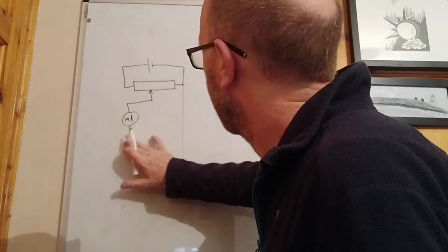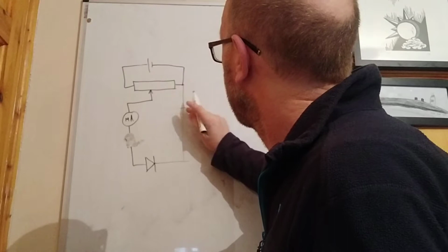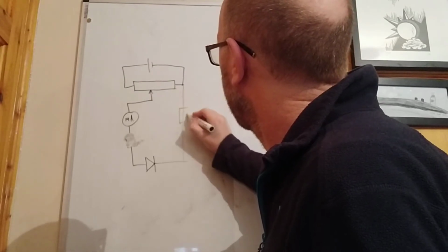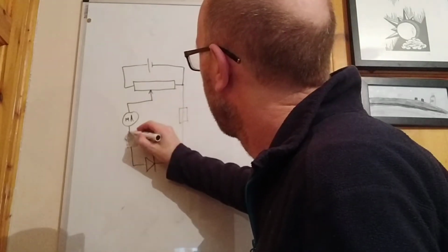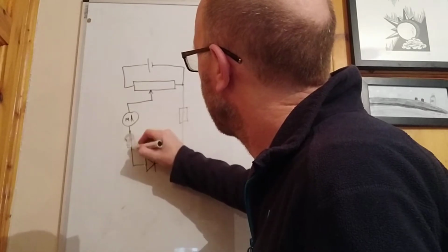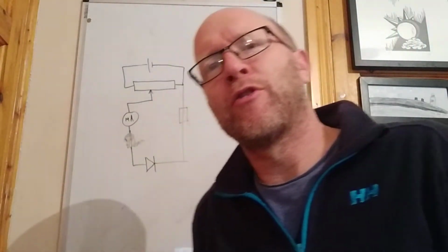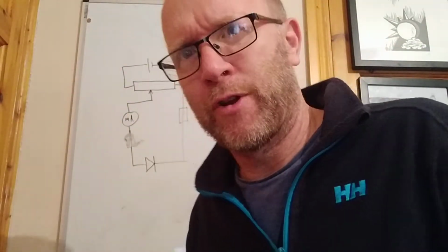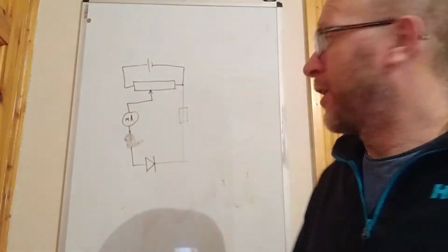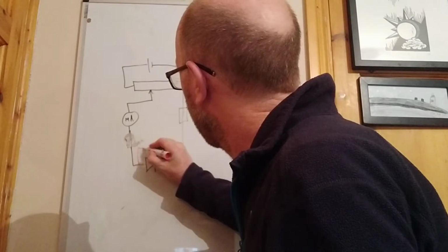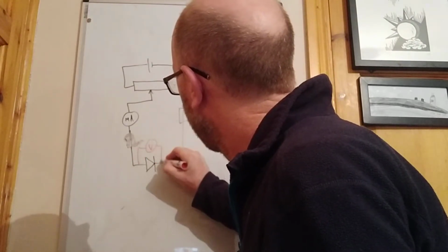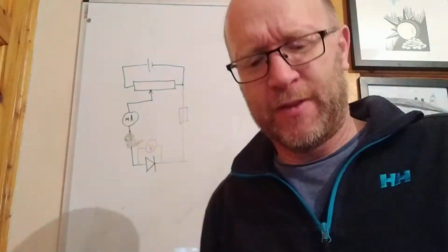Sorry, I'm going to put this resistor over here. We're just putting that in for the crack, really. And remember, at all times, to get the voltage, you apply the voltmeter across what you're interested in. So I'll use the red, as we used to do before, and we put our voltmeter across here. That's fine.